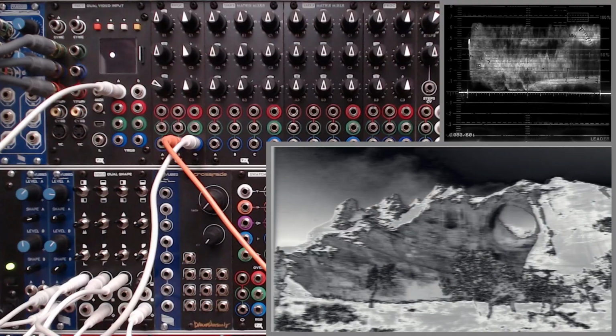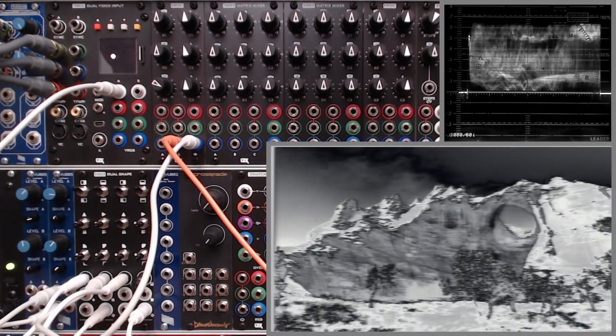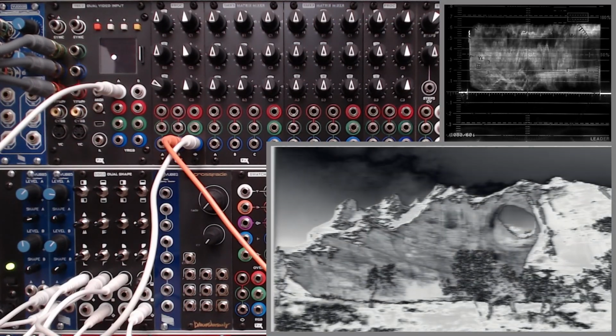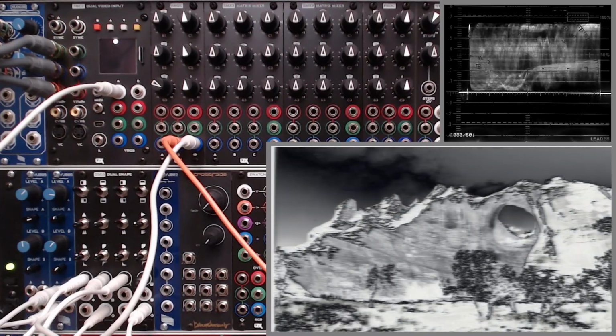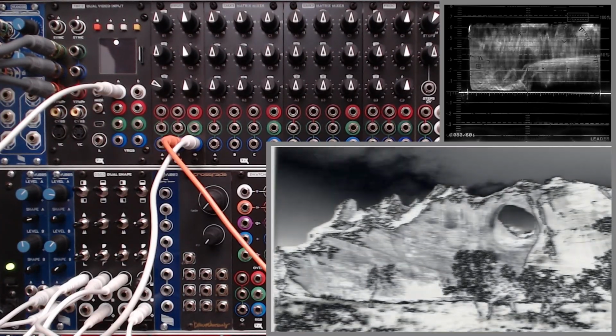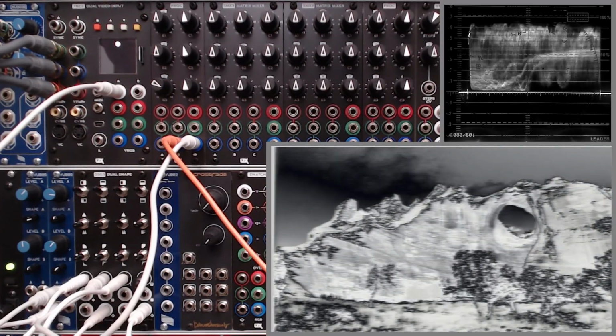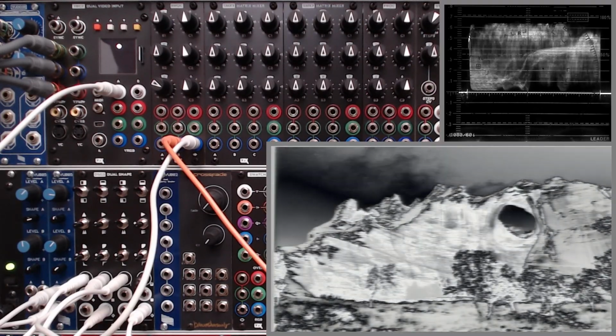Now we come to the magic, the killer app of DSG3, color cycling, or in this case, luminance cycling. I'm only cycling the brightness of this image. The ingredients that you will need to achieve this effect are some kind of video image. It could be a natural one like this or a synthesized pattern. You'll also need a low-frequency sawtooth wave. You'll need an absolute value processor and a folder or frequency doubler or rectifier.